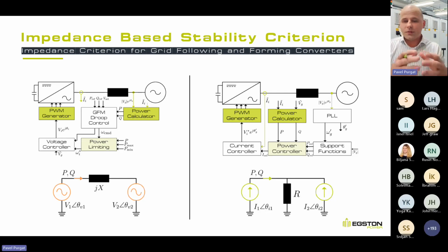So for the equipment that we will need, it means it needs to be able to impose the operating point, impose the perturbation, and it needs to impose the perturbation both in the voltage and in the current. So we need both sufficient current and voltage bandwidth.